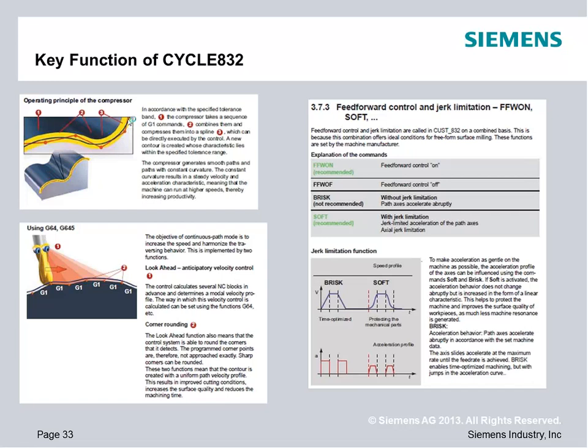They had a hard time outputting them because typical controls could not read splines, so they had to put everything into these point cloud type scenarios. So for all intents and purposes, we're reverse engineering your part. We're transposing the spline through these series of points, and your chordal tolerance is the restriction as to how free we can make this spline to figure out what the shape was in the first place.